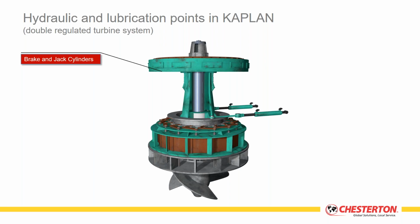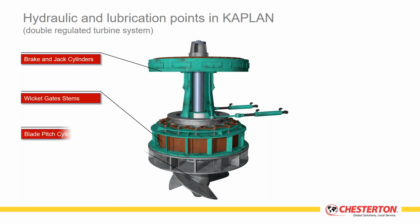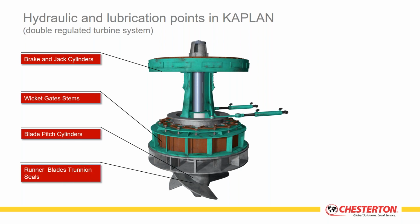What kind of seal, fluid power and lubrication applications are we talking about in case of Kaplan turbines? First of all, the brake and jack cylinders next to the generators, the wicket gate stem sealing and bearing applications, the blade pitch cylinder, the runner blade trunnion seal.